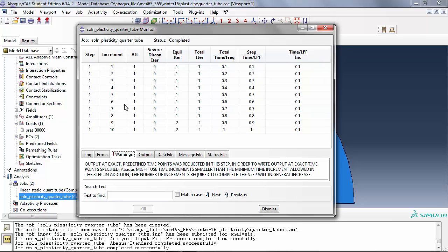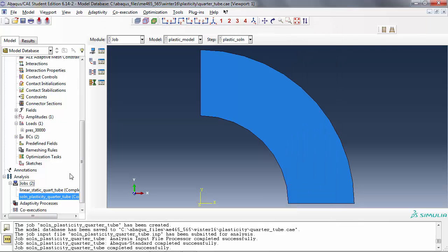But you notice now I'm having multiple stuff going on here. Step 1, how many increments did it take to solve? 1 increment, how many iterations? 1. With 1 iteration at each one of these initial 8 increments, we were able to achieve the convergence, because that was a pretty regular problem. The 9th and 10th iteration required 2 iterations. There's a good chance this is where things went beyond the yield point. But you have a solution, theoretically.